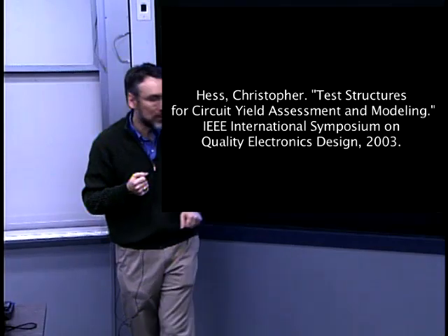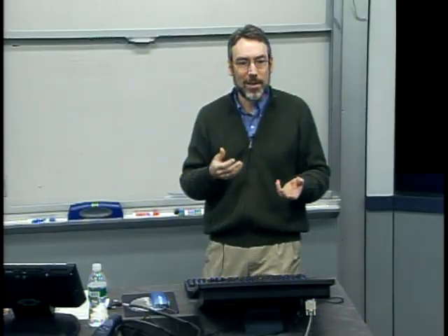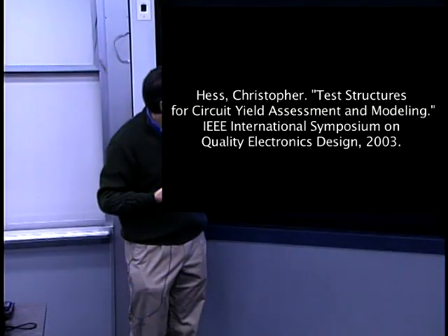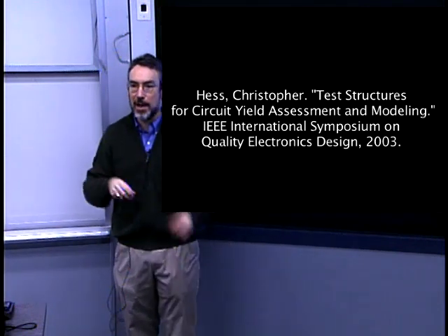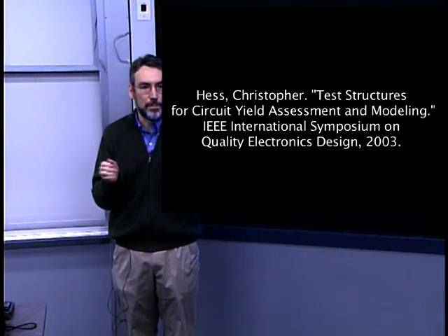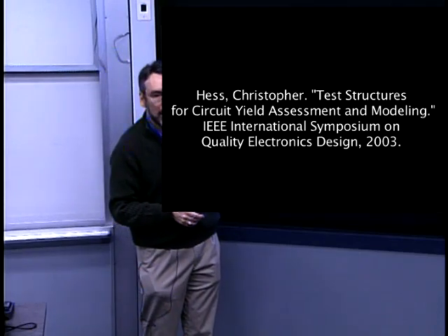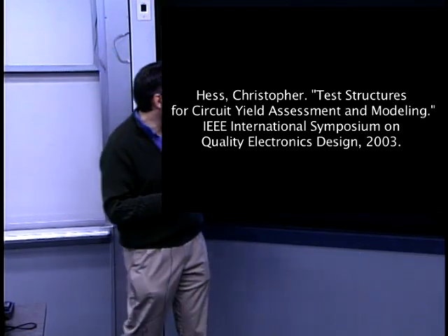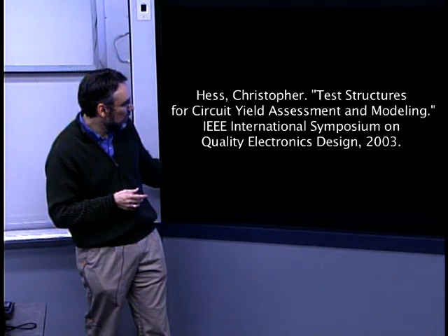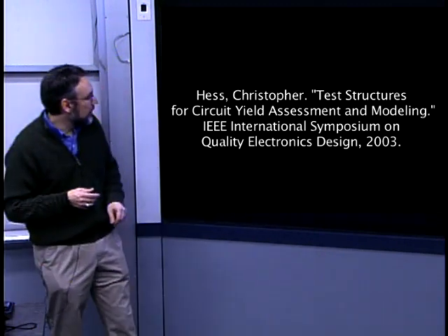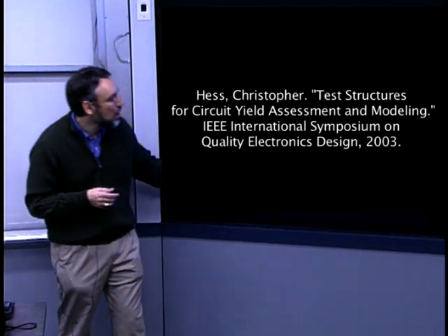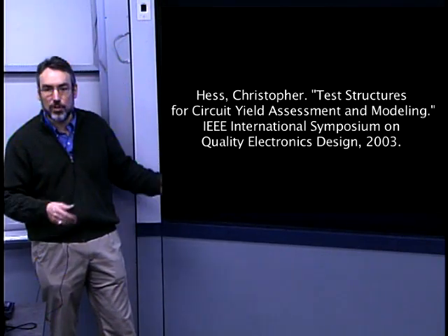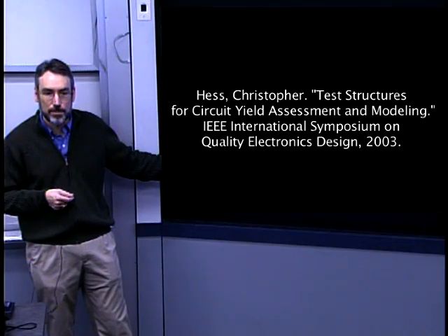And you can also use this structure to characterize the size of these defects, especially if they're relatively large. So for example, if I had a big particle that bridged 3 of these lines, I know within certain bounds that I've got a particle between some size interval. And so that's what's shown over here, a defect count as a function of the size in microns of different particles for these large area sampling structures.